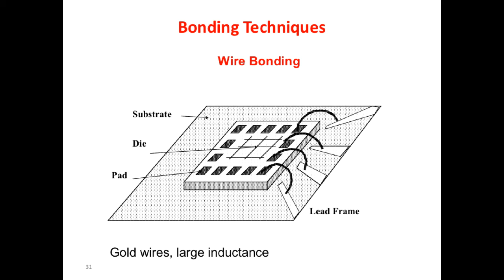As you have seen, at the end of a fabrication process, you have some small pieces of silicon, which are called die, D-I-E, that contain the complete chip. And this is, for example, a silicon die, this small rectangle here. The external contacts for input and output are typically placed here in regions that are called pads. These have to be connected to the outside world.